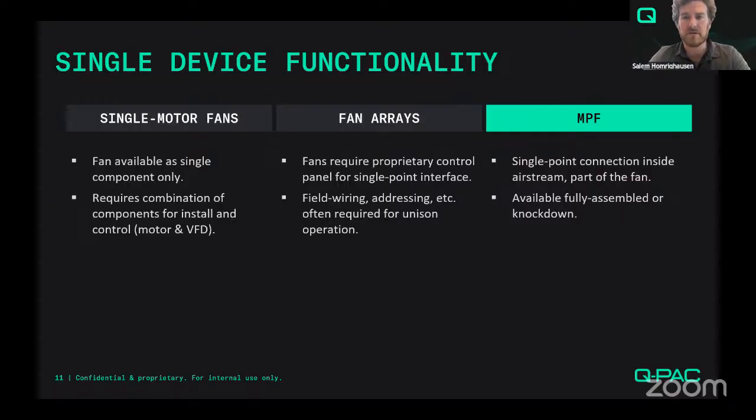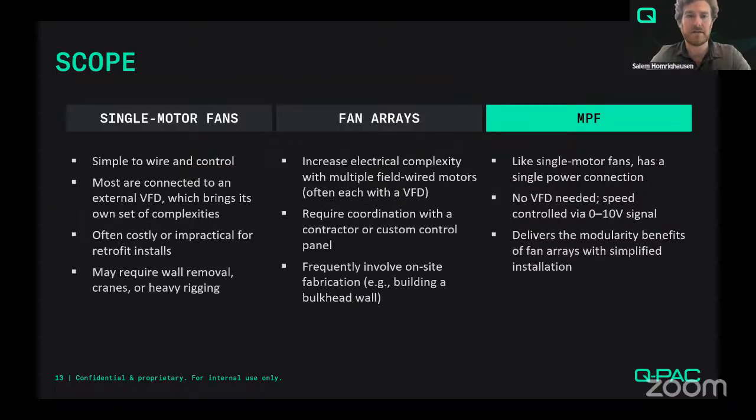Once it's installed and assembled, you're going to have that single point of power and controls going from the fan controller to either the panel board or the exterior control panel, and the controls point at your BMS to just control it as a single unit. So you can think of it as, if I took the VFD out and ran my power to the multi-motor plenum fan control panel or to the fan controller directly, would I have to change anything? And the answer is no, because it's a single device, right? So that's the idea there.